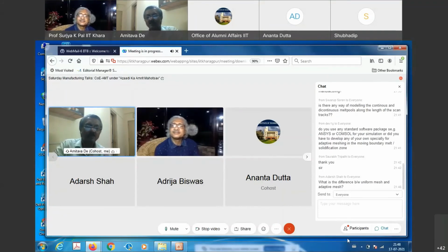So imagine a situation that you have a model of 10 layers, 10 tracks, something like that, of 10 mm by 10 mm by 5 mm size. Imagine that this is totally built by, if you take a 1 millimeter or 0.01 millimeter unit cell and you have to model this with this cell, you have billions and billions of such unit cells to completely model this. And the more number of such nodes, the more the number of degrees of freedom.